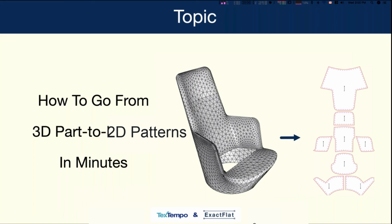You can't go directly to the 2D workflow, but what you can do is, using the piece creator, you're not limited only to 3D models. You can select and form pattern pieces from 2D planar pieces, and that will effectively skip the flattening workflow. It just goes straight into the 2D environment from there. So you still need to go through the piece creator, but you can bring them directly into the patterning environment afterwards. At that point, you can choose to add seams, hardware, markings, all that kind of stuff if you want. It really depends on the state of your pattern at that point. You can recreate it in ExactFlat, and then finally, you can bring it into the nesting component for nesting.